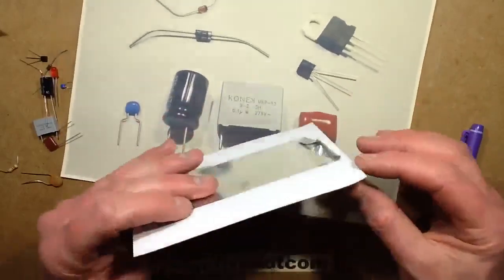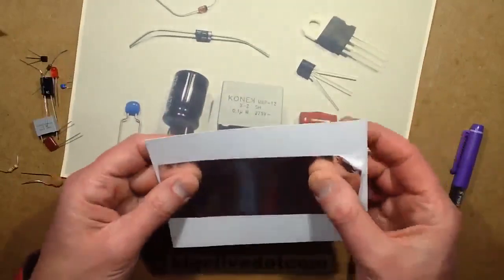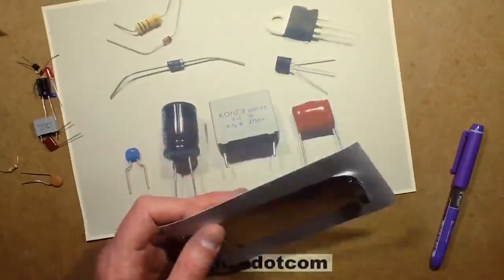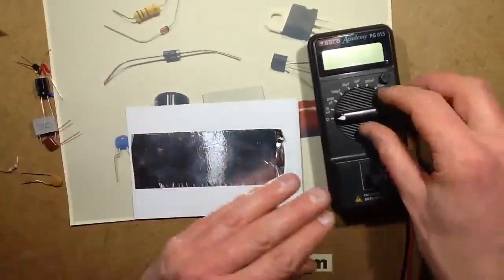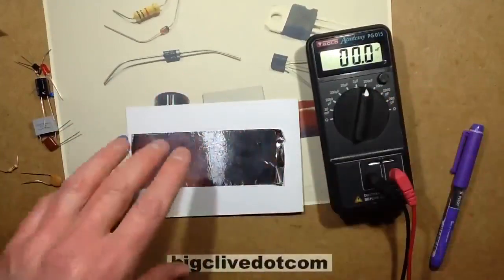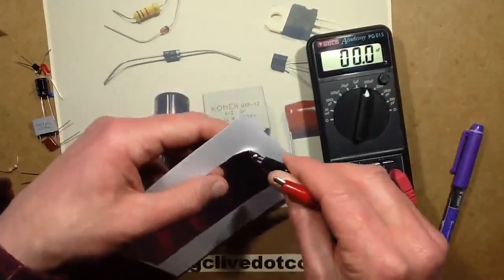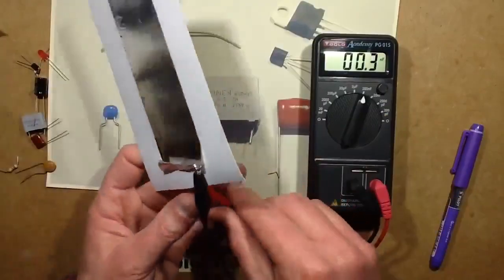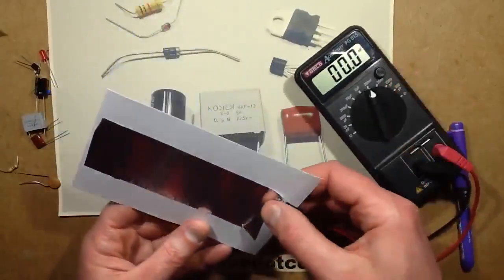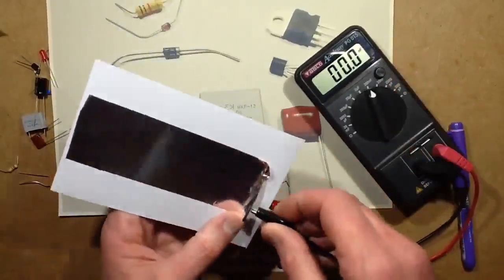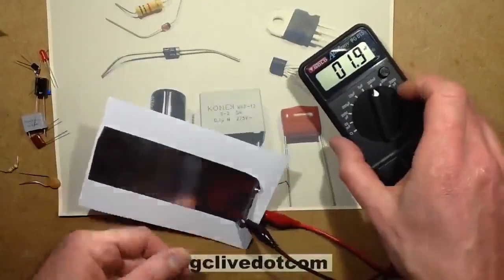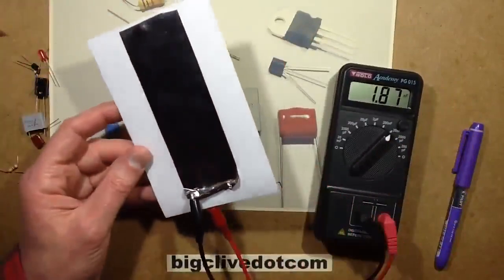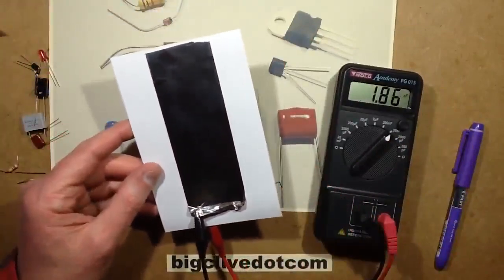And you'd think, you know, this card is very thin, so it's going to be a modestly high value of capacitance, but that's not true. This is not going to be a high value of capacitance at all. So let's be optimistic and say 200 nanofarad. And I'll connect it one side and the other side, and I'm actually connecting onto the adhesive side here. My capacitor measures, oh, that's terrible, isn't it? It's 1.8 nanofarad. It's not very high at all.